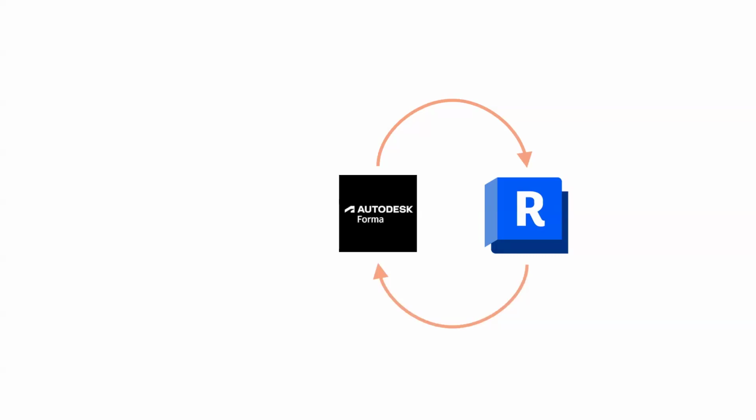Let's say you wanted to run a sun hours analysis on it to see the impacts of some type of trellis or covering that you added, and you want to see if that affects the sun hours analysis, you can push it back to Forma and run the analysis on that mass.